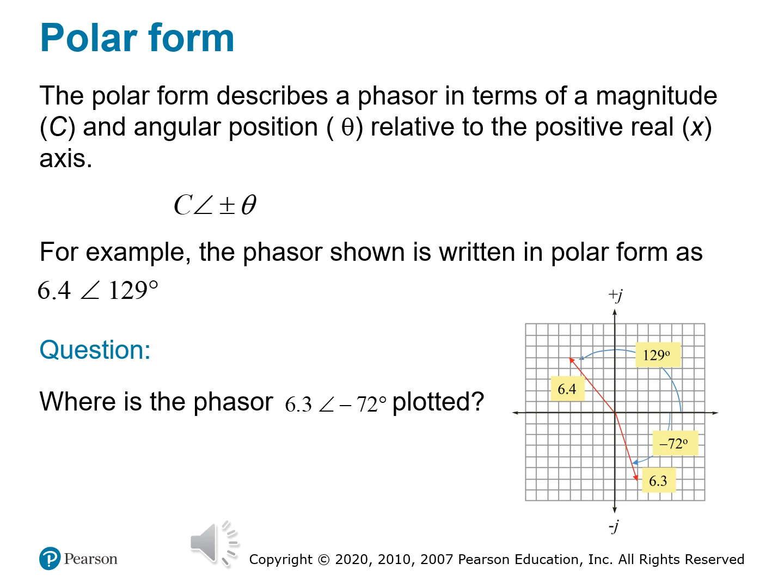So let's do a quick recap. Use rectangular for addition and subtraction. Use polar for multiplication, division, and angular analysis. Angle direction defines a phasor's orientation. Combine forms when you need to for full control of phasor algebra. And again, up next, we're going to connect all this to things like Ohm's law in the complex plane.